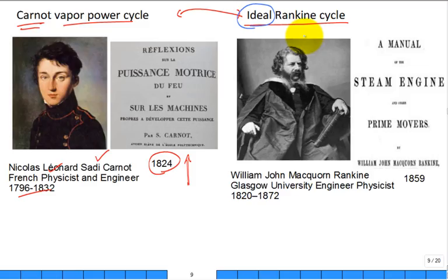That sounds like a pretty good system. But the question is, and it's hard to grapple with, is it just as good? Are both of these just as good? Is the Carnot vapor power cycle, which has no friction in the turbine, no friction in the pump either, just as good, or is it a little better or a little worse than the ideal Rankine cycle? Same boiler pressure, same condenser pressure. Trying to compare apples to apples, not get them mixed up. But would they be the same?